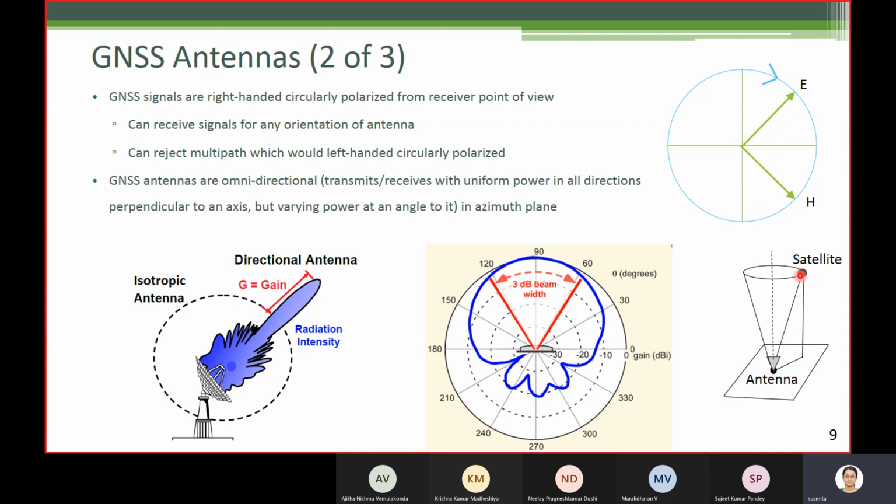How does the gain vary on that vertical plane that we just talked about, this line, and this line? Just connect and imagine a plane that contains these three lines, and then extend the plane on the other direction. So on this plane, how does the gain vary? We know that the gain varies. The antenna will receive signal with varying gain on this plane.